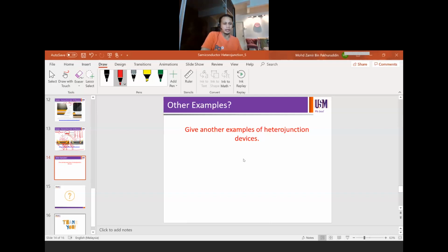It won't work, right? Unless you want defects lah. If you don't want defects, or you want to minimize defects, minimize recombination, and avoid the devices not working, then you need to pay great attention to the design in terms of lattice mismatch and stuff.